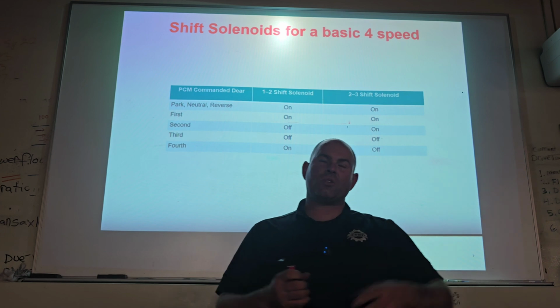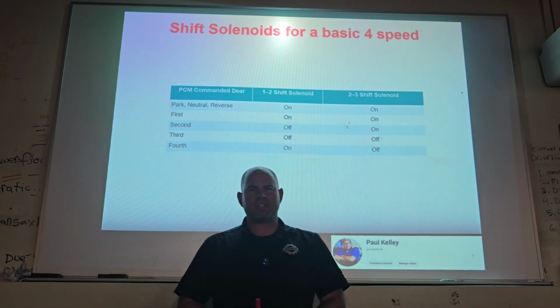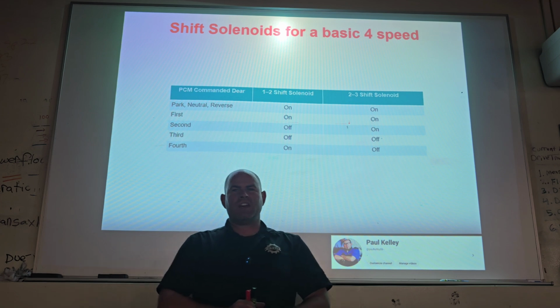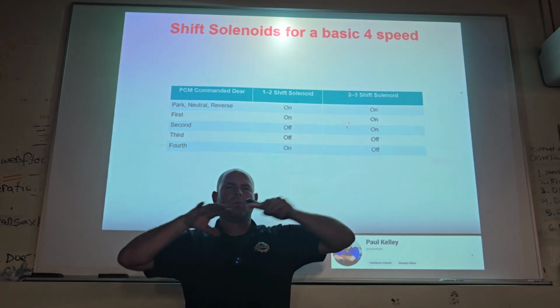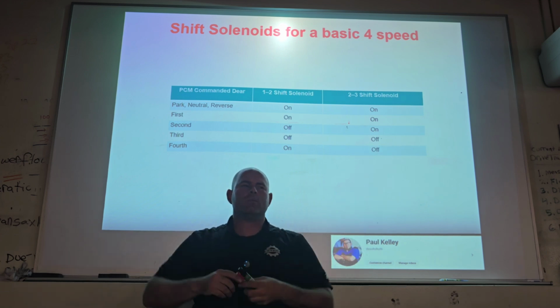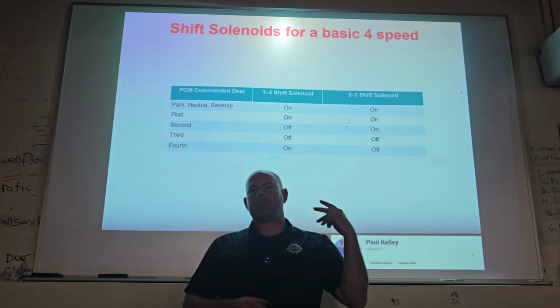Check for codes, but it has no communication. So I like that idea. You're right. That's why I checked for codes, but it said no communication, right? If I'm using one computer to talk remotely to the TCM and it won't communicate with it, what should I do? Fuse is a good idea. I could look to see if the TCM is plugged in.